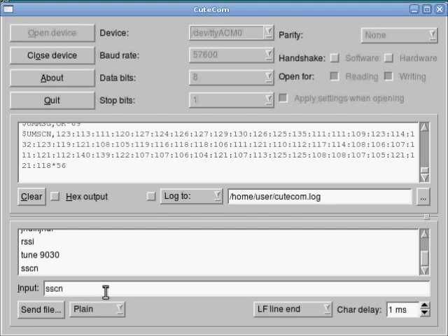So if you run this, you probably want to run it a couple times, and we just ran it again here to see if the pattern persists. It looks like we're still getting 140s on these two channels. So that's still pretty high, but generally this is a pretty good noise floor, and this is not bad at all.